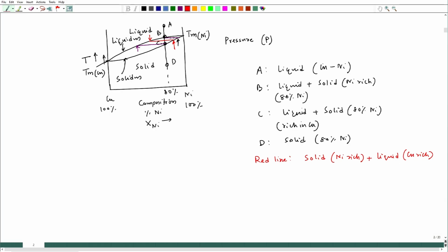We could also see different equilibrium lines, liquidus and solidus, and as I have seen in case of single component, on the line the two phases are coexisting, and beyond that line, for example, A to B, if it does not touch B, a single phase is existing, and C to D, if I do not touch C, I could get all solid, but in between B and C, I could get two phase mixtures.